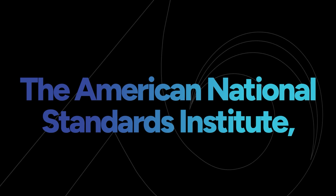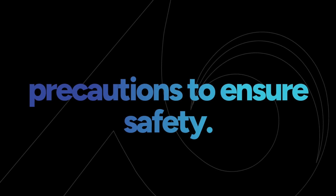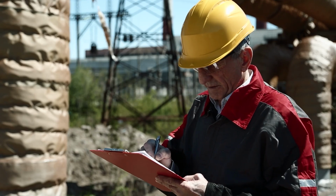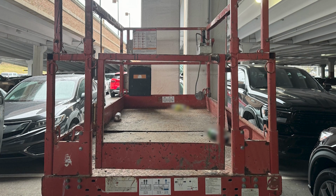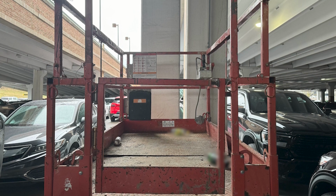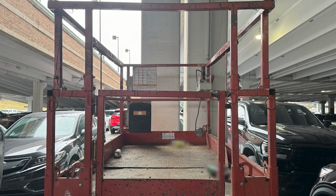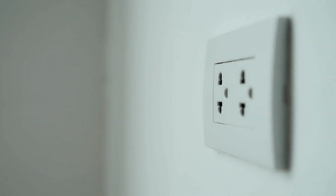If repair or maintenance is needed on the scissor lift, the American National Standards Institute, or ANSI, recommends taking certain precautions to ensure safety. First, all manufacturer precautions and directions should always be followed. The load should be removed from the platform and the platform completely lowered before repair or maintenance begins. The platform should be secured to prevent accidental movement during the repair. All controls must be off and all operating features secured to prevent accidental movement. Disconnect all power sources before working on the unit.